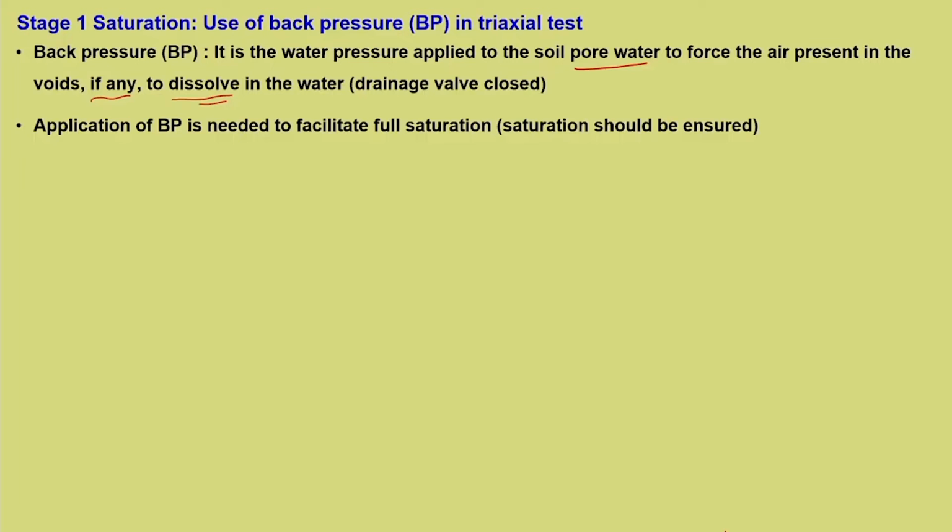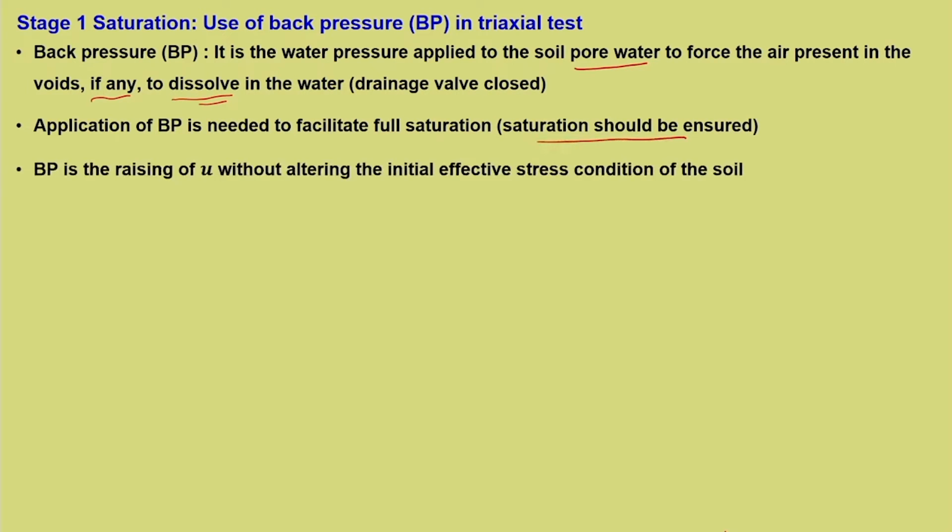So, water displaces the air and hence it achieves complete saturation, which is a condition mandatory before consolidation or loading. Application of back pressure is needed to facilitate full saturation, and saturation should be ensured.